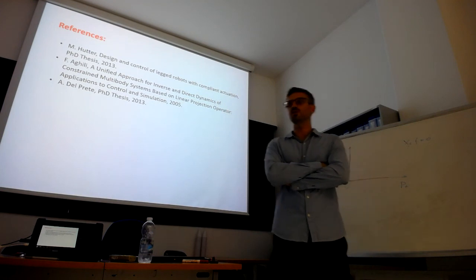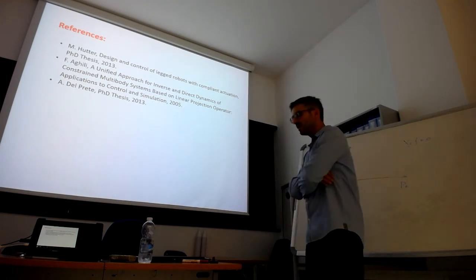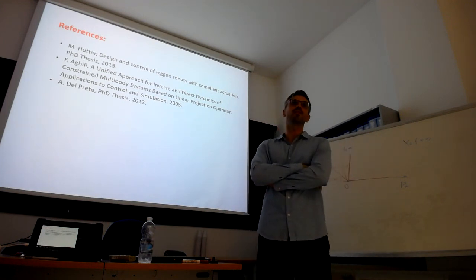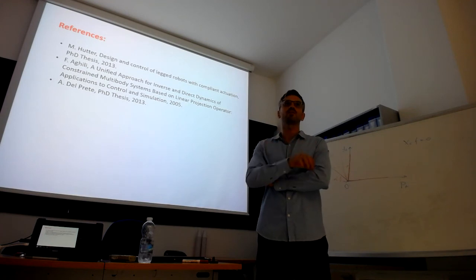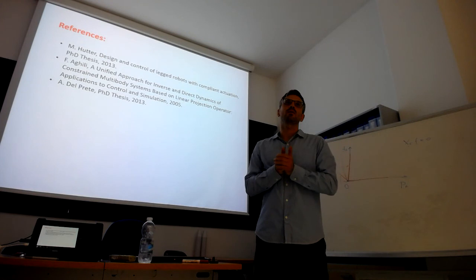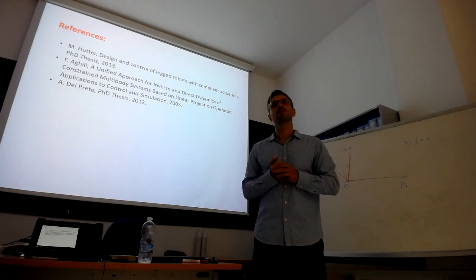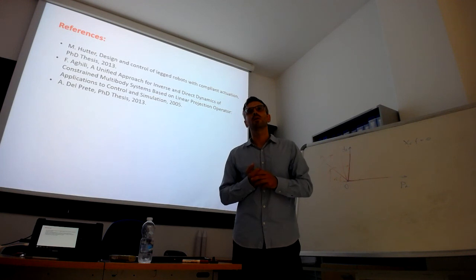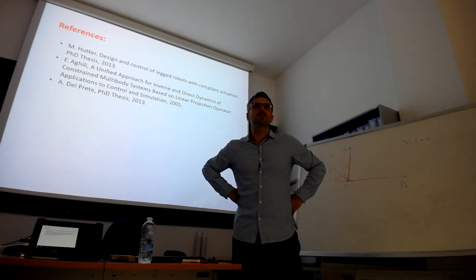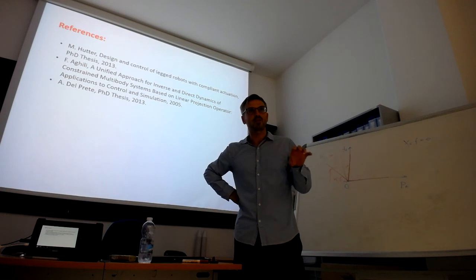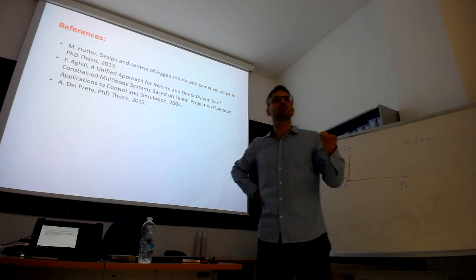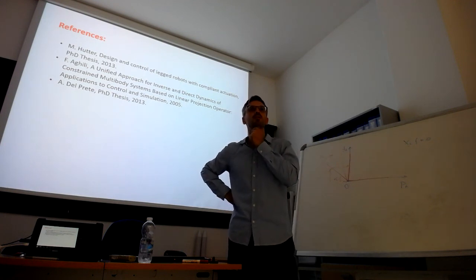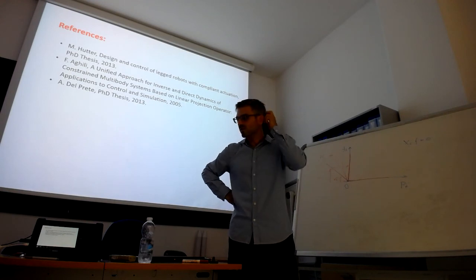For an unconstrained QP, the pseudo-inverse is equivalent, but this is a constrained QP in the case of the Gauss principle, so it's not equivalent. Absolutely, you have the contact constraint added on top. So how does the solution become equivalent for both of them? Let's say if I were to take only the pseudo-inverse and then solve the same problem with the QP, with this formulation, would we have the same solution? I would need to think if it's possible, but probably it's equivalent because you enforce the contact constraint as a Lagrange multiplier, and then you solve the QP, and probably you will have the same equation in the QP solution as in the case of the pseudo-inverse.